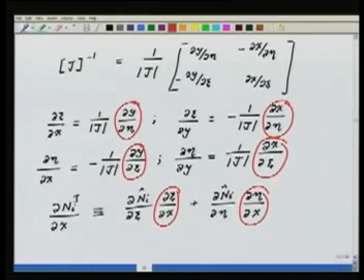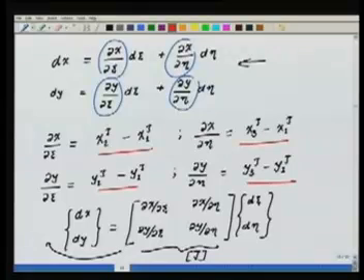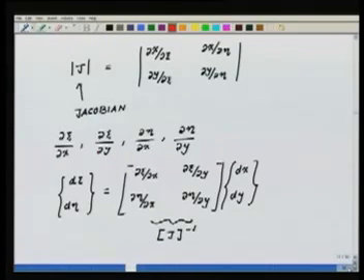This is true only for the linear maps of triangles. We'll see that when we go to quadrilaterals, the Jacobian will no longer be a constant. Again, let me see what we have here. Given these entities, we can plug them in and obtain all the quantities. So for the element, I have to input the three nodal coordinates, x1, x2, x3, y1, y2, y3, and I can construct the matrix of the transformation.